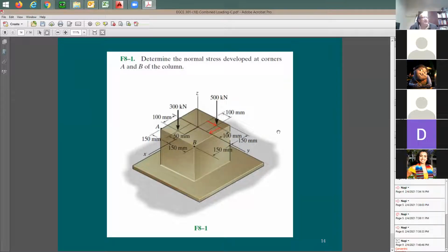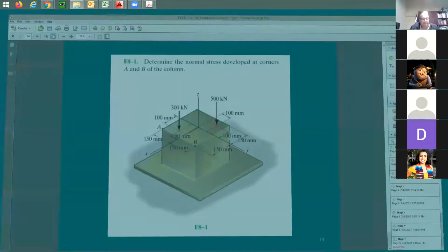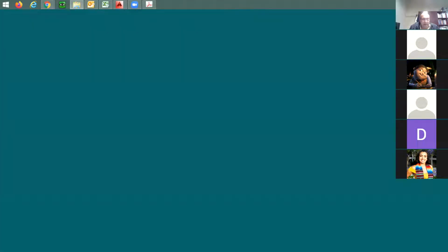So in a case like this, the equation is going to be a little bit complicated. We call this biaxial. When you have Ex and Ey, we call this biaxial loading, but we're not going to be doing it. Usually, we're going to have just uniaxial when it comes to moment and stress distribution. Questions? We're good? All right.